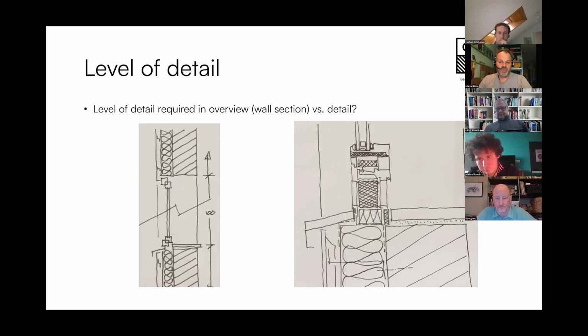Because you may want to talk to someone about the general modules, for the architect in the early starts. He's more interested in where the unitized facade ends. Is it above the floor plate? Is it underneath? What defines, at the very end, his play of lines and the proportions of the facade components and so forth, while you do not need to give exact information on the mounting brackets at the back or whatsoever in that discussion.